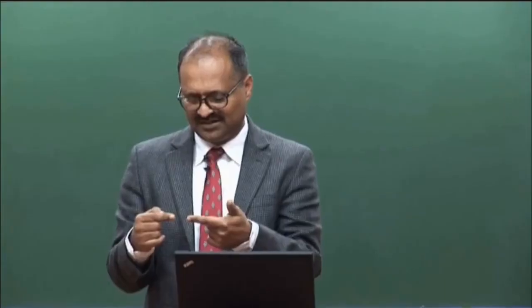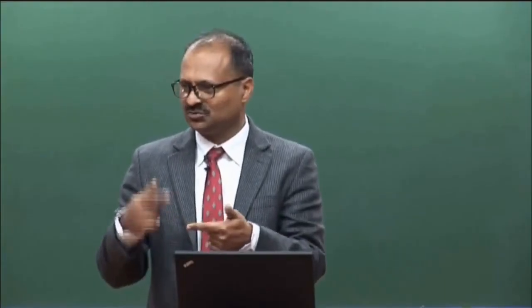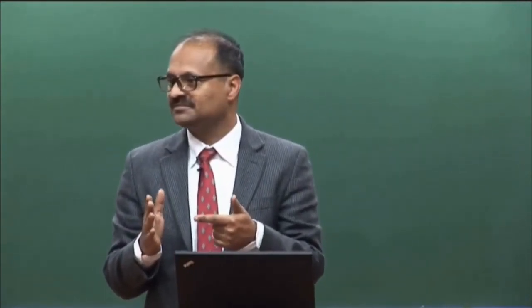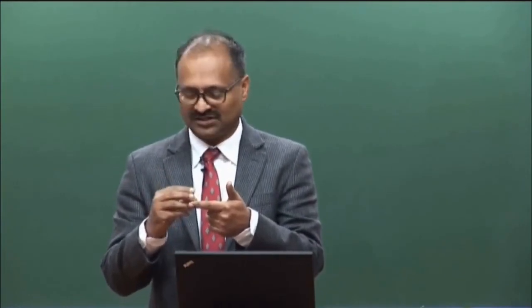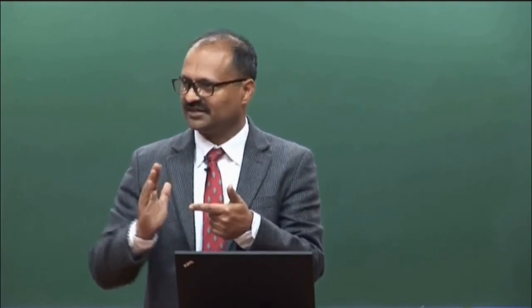So if you're mounting these kinds of things, what you realize is that, look, I just want these two thetas to be coupled. Everything else I don't want to be coupled. So I want to mount this potentiometer such that it is free to translate just a little bit in this direction, maybe move back and forth so that the coupling works. And if these two shafts are not aligned correctly, I want this to be able to align like this, but I do not want it to be able to move in this plane.